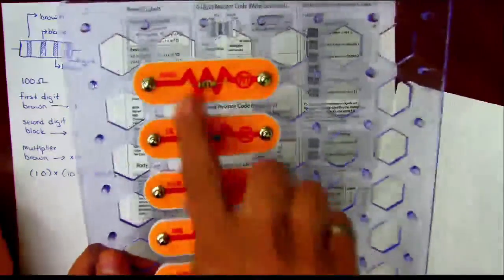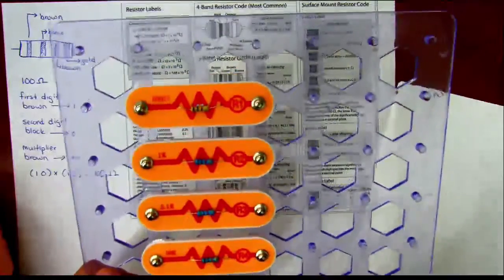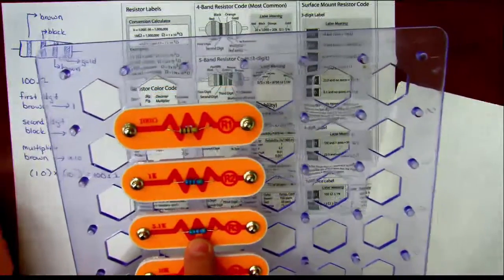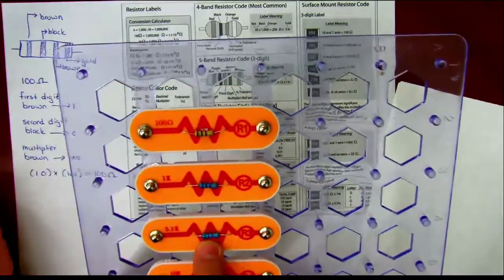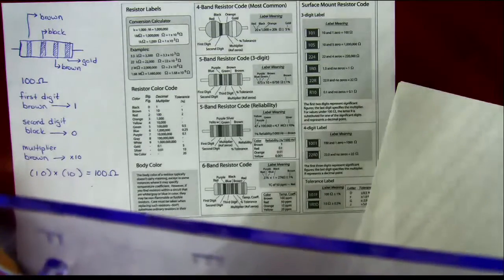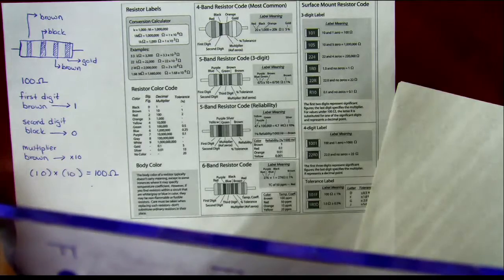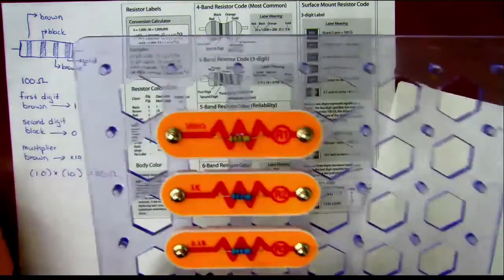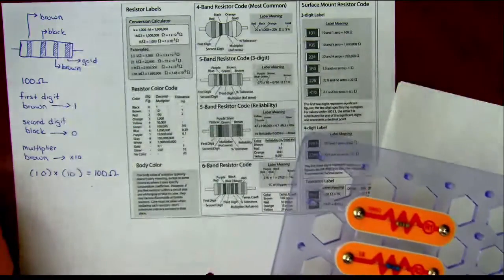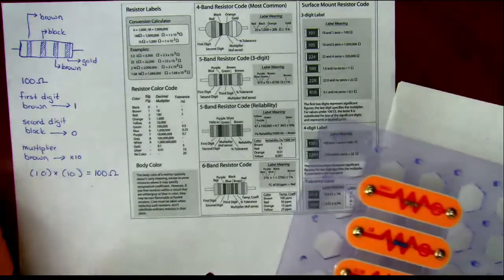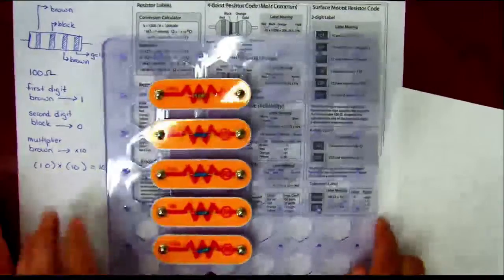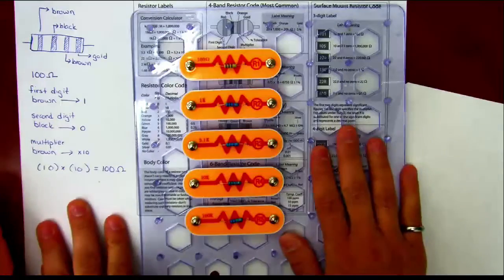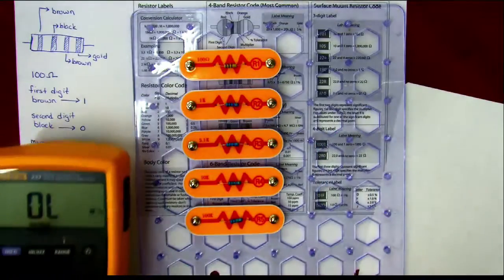I put 5 different resistors on here, and their values are written here. If you want to try a different one as I'm passing it around, you can look at this 5.1 kiloohm. You should be able to do the band colors. If you're having issues with color, it's green, brown, red, gold. That gold, the last one, is your tolerance, and that's just your tolerance for the number coming across there.